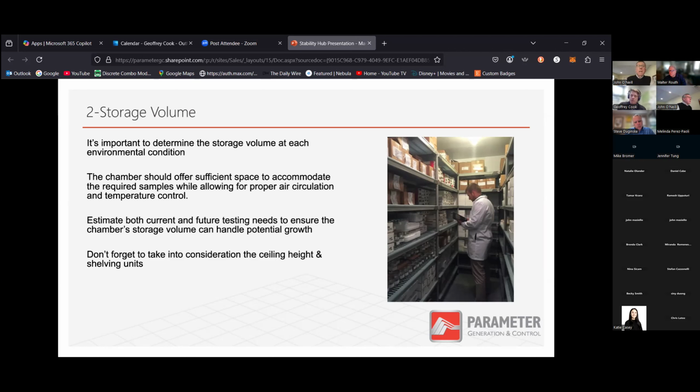Certainly, John. So we do build light sensitivity chambers. Depending on the type of light, the intensity and density of light you're needing, we find that the light chambers need a significant amount of airflow to control that heat and still maintain our temperature and humidity. So we typically build small benchtop cassettes as light chambers with an internal volume of probably just about 6 cubic feet.